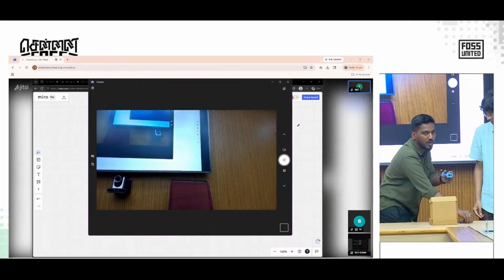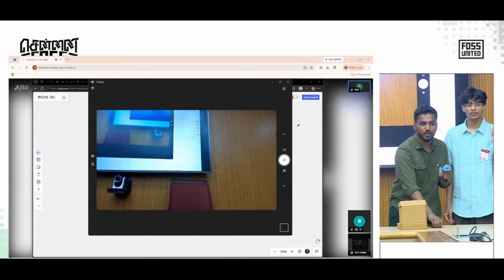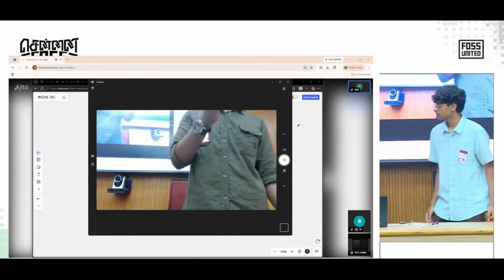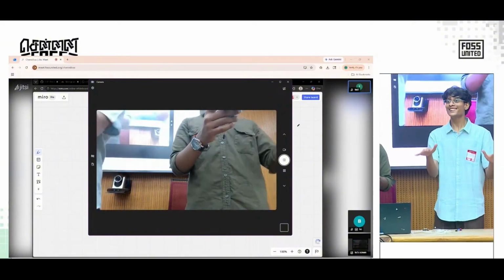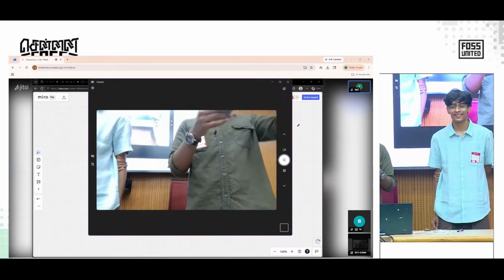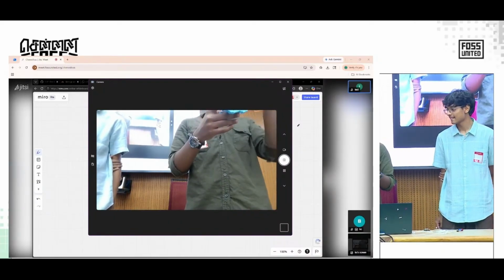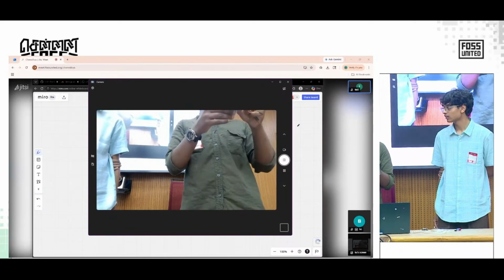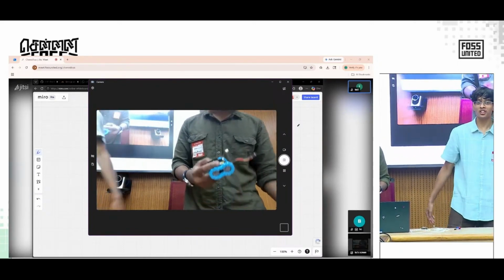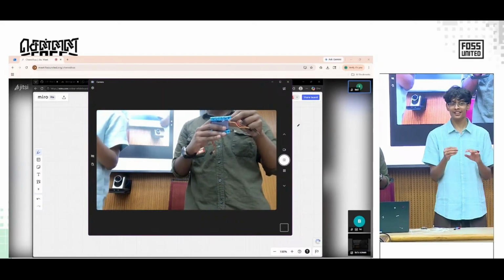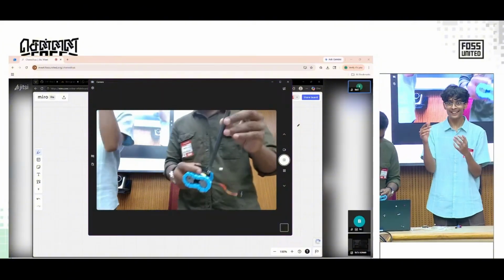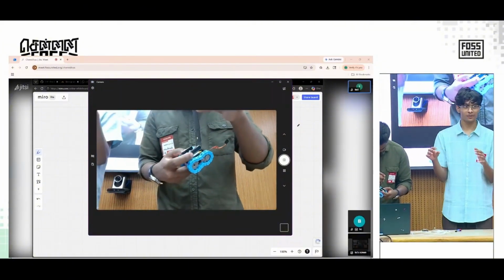You don't have to screw all four in. You can just do any two corners. That should be fine. And when you think of batteries, if you try to screw it in too hard, it is going to dig through the battery itself. So make sure you just do it halfway, not all the way. If you accidentally puncture your battery, you might actually start a fire, so let's not do that. Just tighten it lightly. Don't push it in fully.